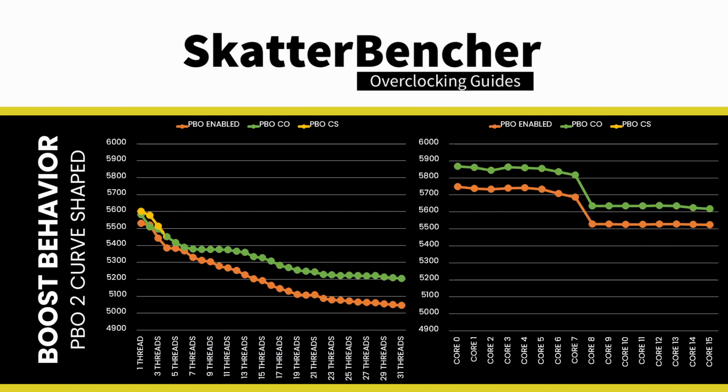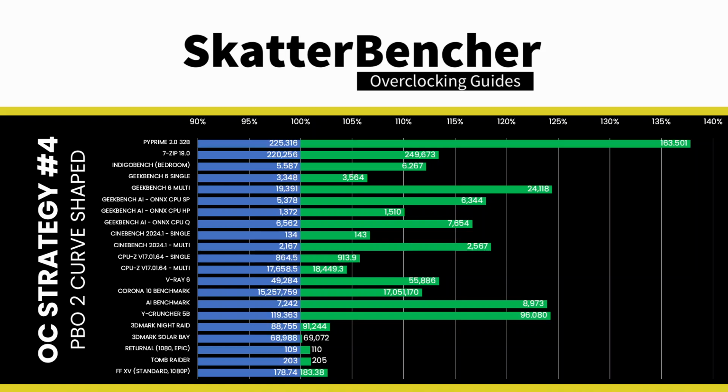After applying the BIOS settings, the boost frequency at one active thread is about 5602 MHz, and the average boost frequency gradually trails off to 5269 MHz when all cores are active. In a light, single-threaded workload, all cores in CCD0 can boost to over 5.8 GHz, and all cores in CCD1 boost over 5.6 GHz. We reran the benchmarks and checked the performance increase compared to the default operation.